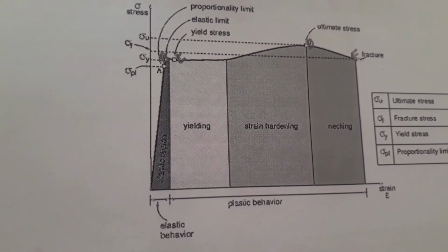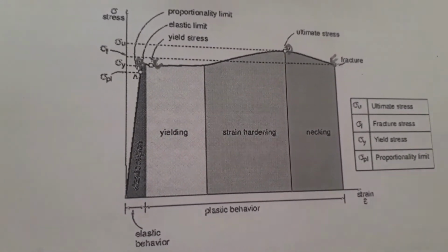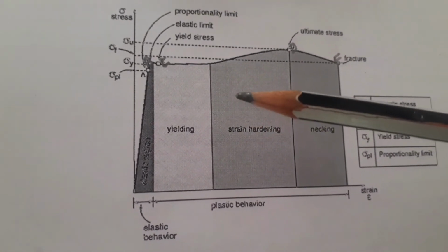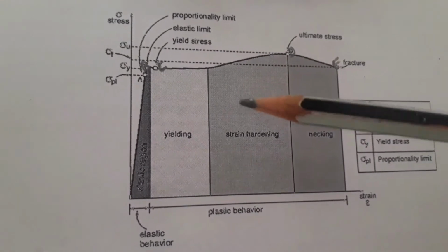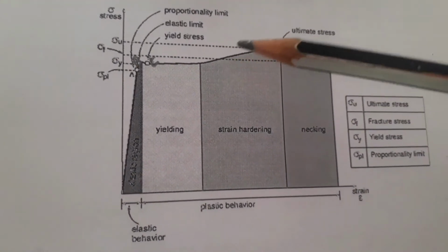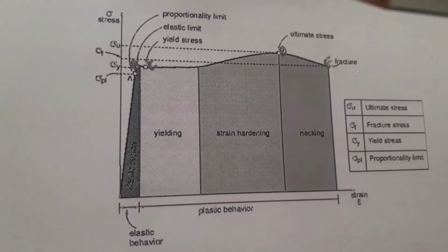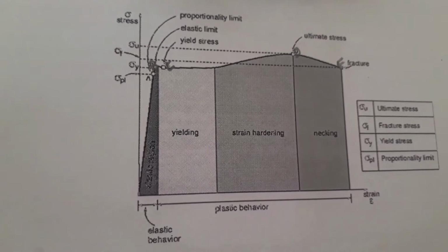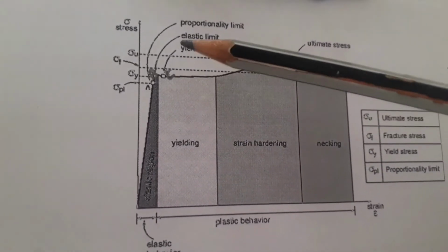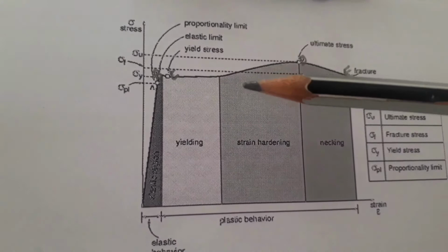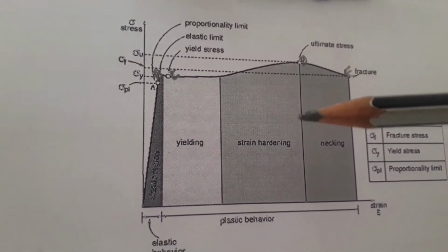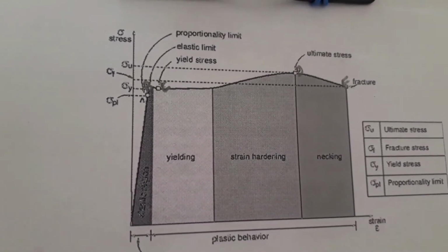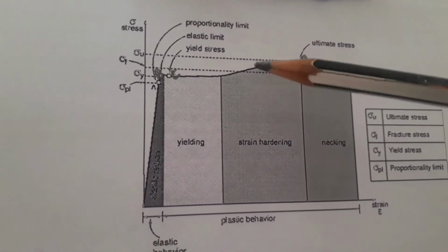Again, the area of elastic deformation is divided into 2 phases. In the first phase, the material stretches proportionally to the stress acting on it. This extension is also called linear elastic or proportional deformation. The point at which the linear elastic deformation is maximum is called proportional limit. Beyond the limit, elastic deformation still takes place. However, the greater elongation occurs in the section under increasing applied force. Therefore, the elongation or strain is greater than the increasing stresses.